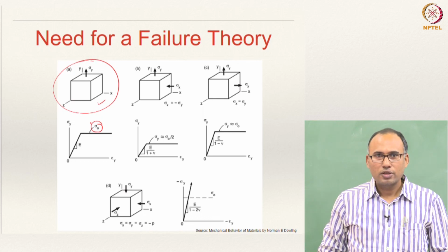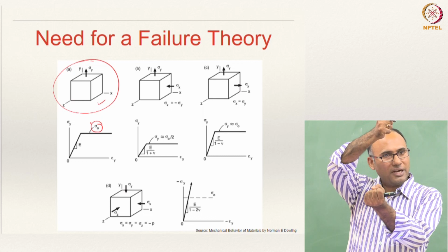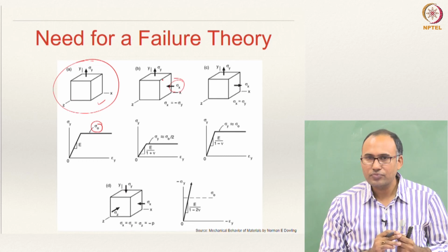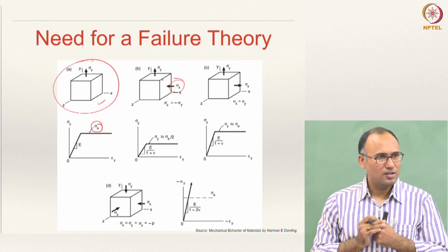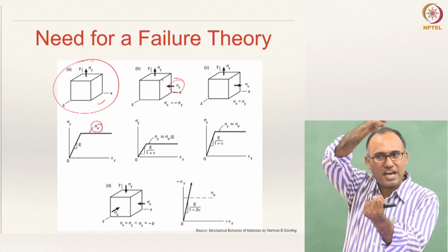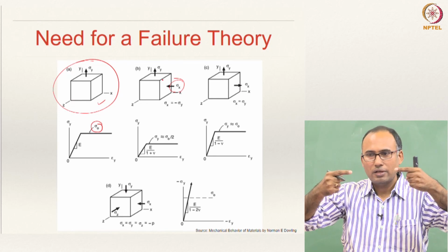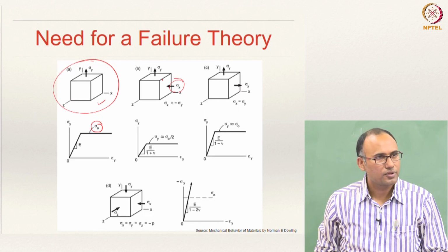Now, you do another experiment wherein this load is there, but laterally you apply another stress, sigma x, but that is compressive. You are pulling one guy in this direction, at the same time you are applying a lateral normal stress, but that is in compression.